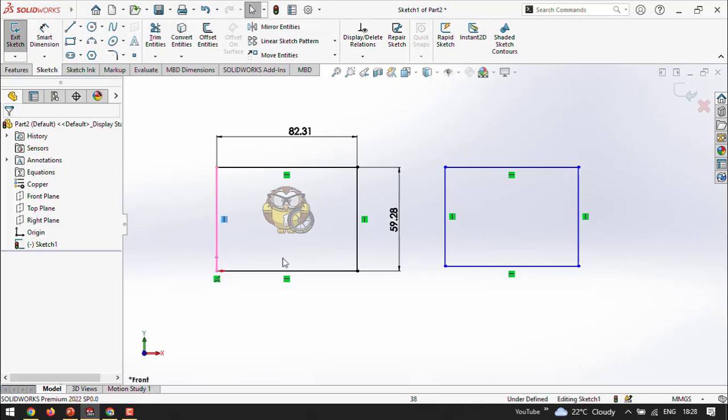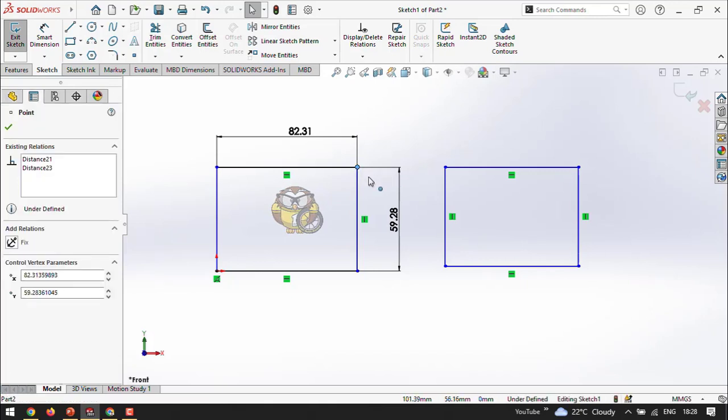I go to delete this vertical constraint. I can delete here also. You just select, I'm not selecting the line. Now I select only this vertical constraint and press the delete key on my keyboard. Now the constraint was deleted. Once the constraint is deleted, see, the blue color appears again. It means there are no constraints. No constraints means you select this point and you can change it.